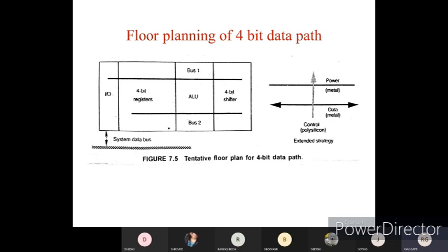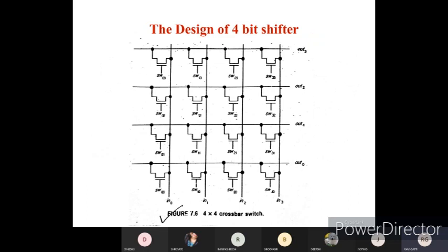What do I mean by accommodating the IC? Where exactly I should place the ALU, where I can pass the bus architecture, that is the data bus and the address bus, how I can place the memory component, and how I can do the wiring and interconnection of the ALU. All those details you need to understand and explain in the floor planning of the data path method.